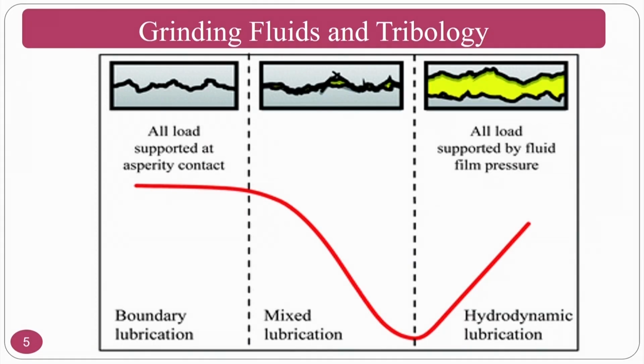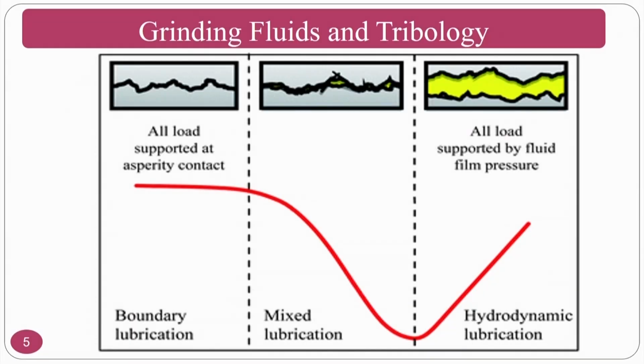So, whenever you want to look at the tribological aspects in the grinding process or metal cutting process, you come across Stribeck curves, and normally there are three regions. Anyhow, this particular thing I will explain whenever I explain the tribological conditions or the tribology of grinding and other things, if time permits. Otherwise, just a glimpse I am going to give you here: this is the boundary lubrication, where metal to metal or grinding wheel to the workpiece will be in contact. Assume that this is my workpiece and the grinding wheel, both are in contact. This is called surface to surface contact.